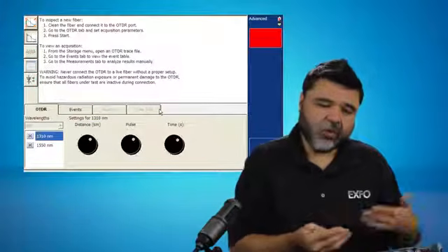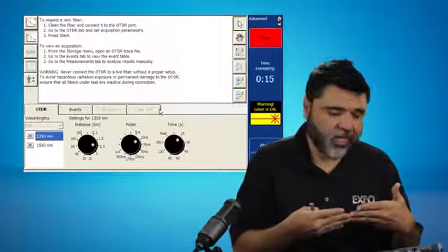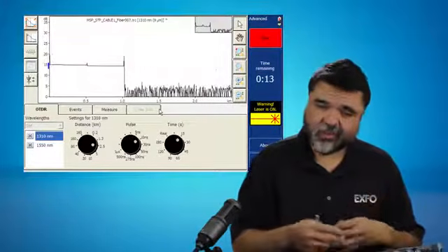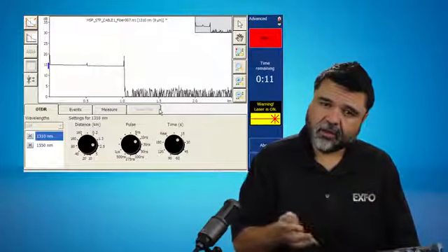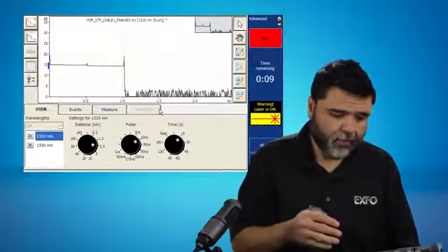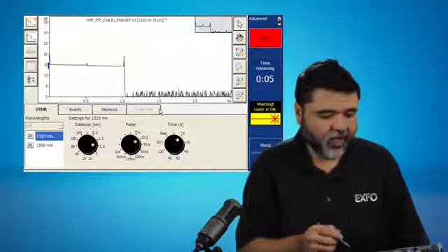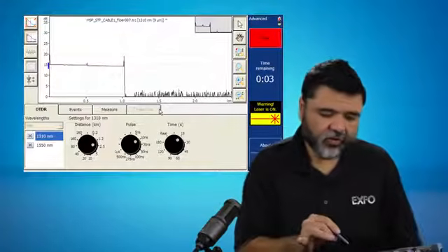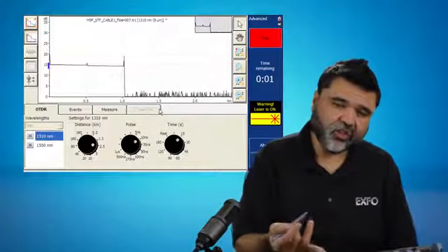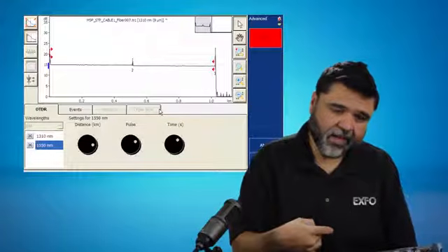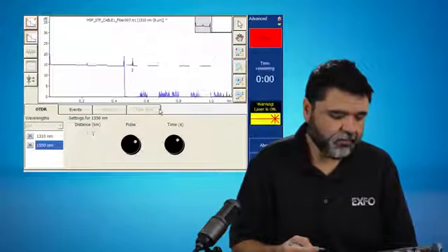So what I ended up doing was daisy chaining my two launch cables together because I want to focus on macro bending as it relates to the different wavelengths. And so in this case, we're shooting 1310 first, so it's going to go in for 15 seconds and shoot 1310, and then it's going to come back in and shoot at 1550.